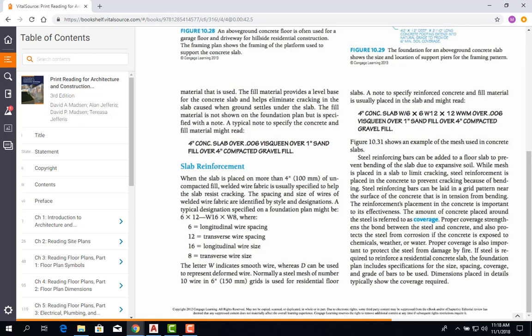Make a form that is about 2 feet, maybe 2 by 2, like a rectangle of a piece of concrete. It compacts very well, but when you try to bend it, more than likely it's going to crack. So to prevent that, you put steel in between. Okay, and that's what's called reinforced slab or slab reinforcement.